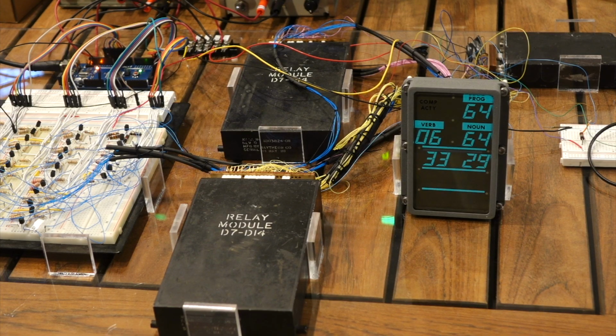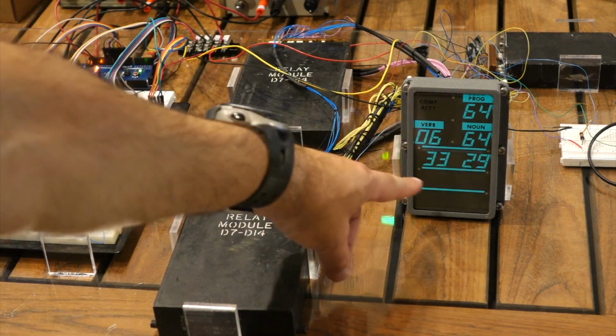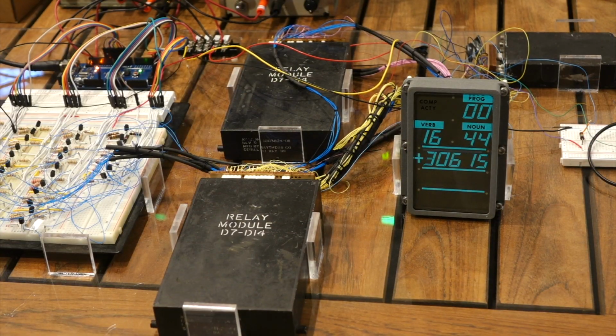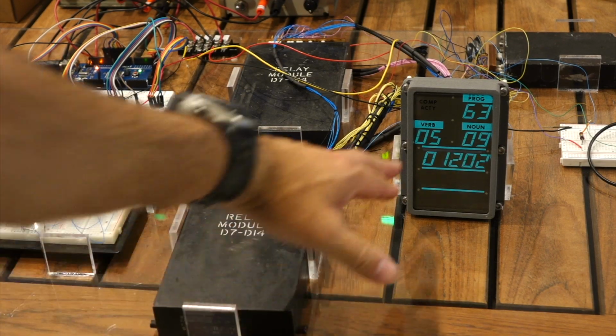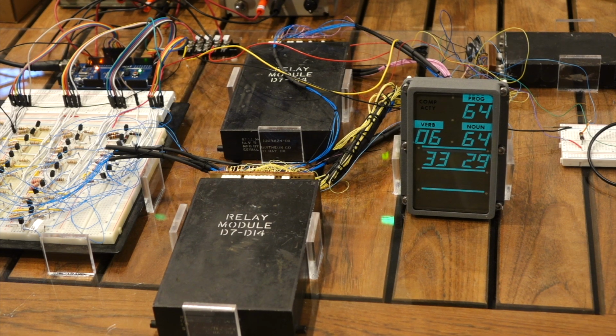Yep. This is your P64, so approach phase angle, and then this is your apogee around the moon. So apolune, I guess. Okay, that's 630509. Show me errors. Yep. That is 640624. Show me, that's the LPD angle and time remaining. So you have to look through the window at 33 degrees, and you have 29 seconds until you cannot redirect anymore. And that's 61.5 miles off on your orbit of the moon. Yes, above the moon. So those are sort of real displays, except we don't have enough relays to do the last 2 rows. Yeah, these are all verb 6 and verb 16, which are all 3 register displays. So if you guys have relay modules, we would like to hear about it.